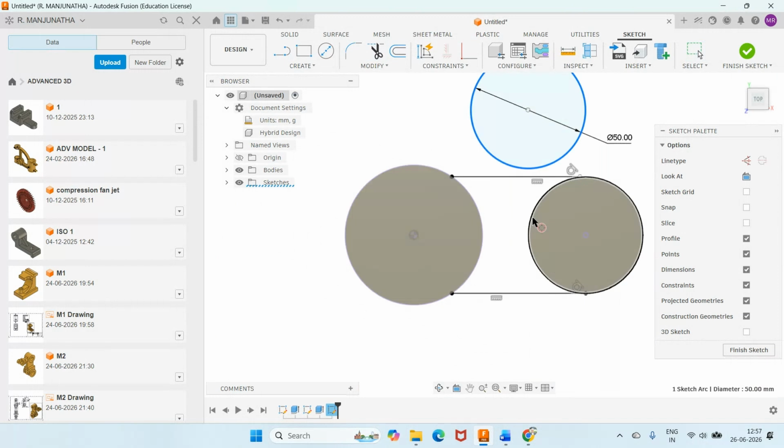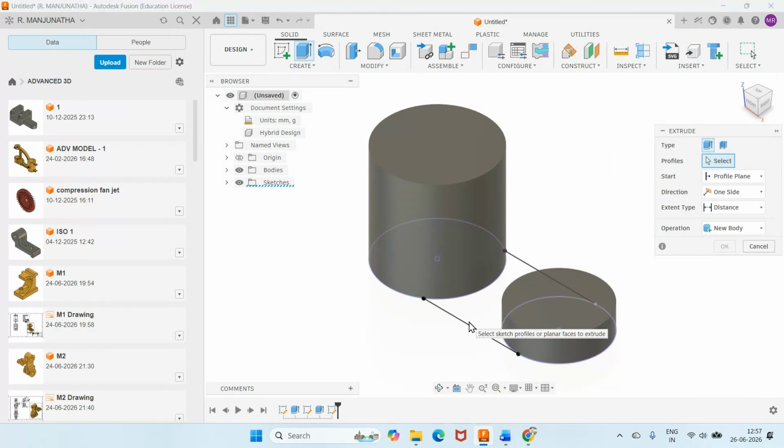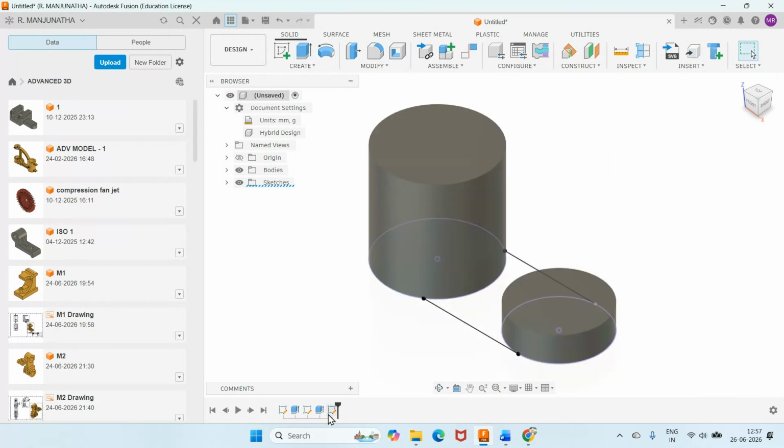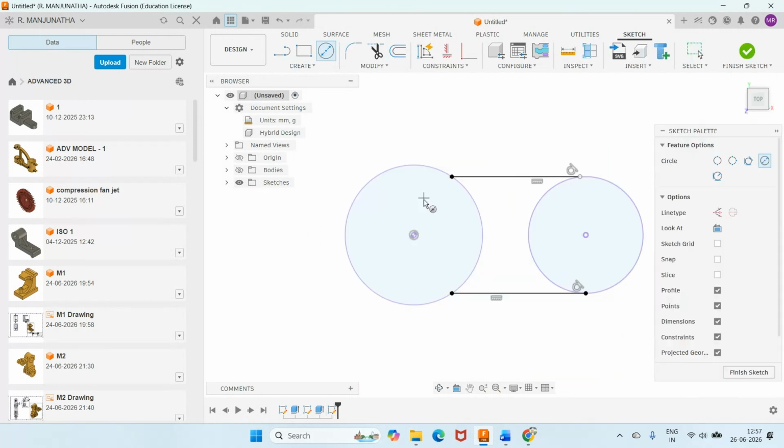Again, it's not taking, that is basically because this is the point which you need to understand. I just go to the bodies, and I will try to trim this particular portion. Okay. So I will go to edit sketch. Okay, now I will go for removing bodies, and I will go for a circle. Select on this circle onto this point, and now I will go for a trim.